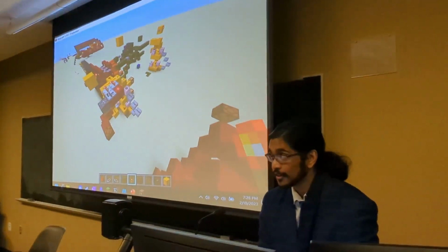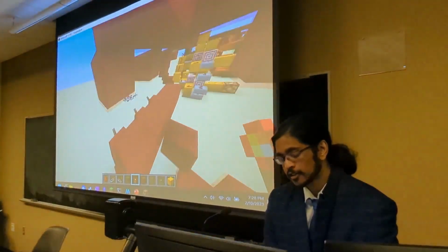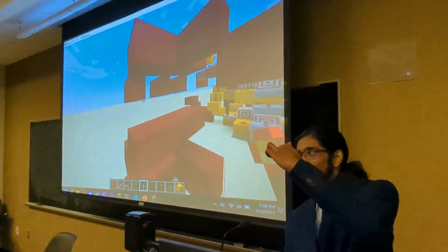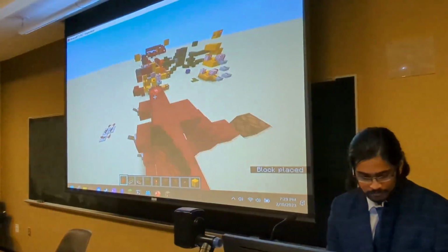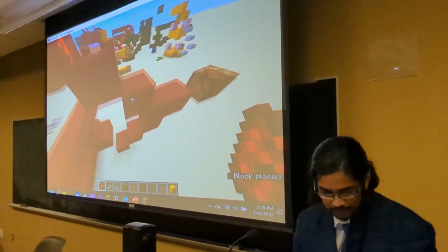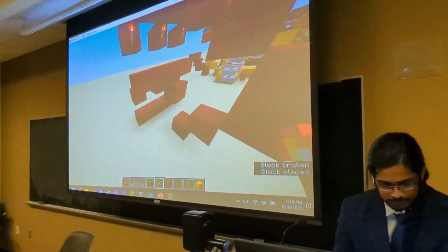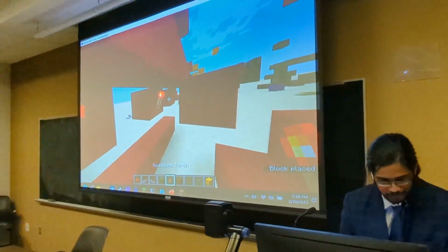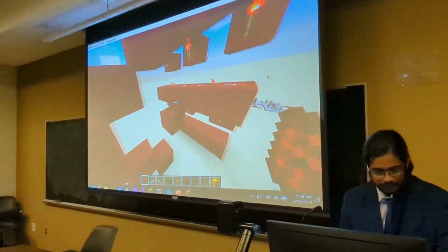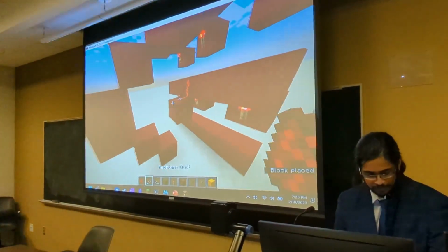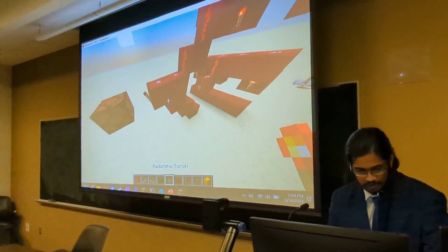Okay, so now we got the memory cell done. Next part is win detection. So all we need, first of all, is to make sure all 3 of the occupied inputs are turned on. So we just create a 3-input AND gate like this. Like that. And then for this guy, we can create another 3-input AND gate like that. And then just take the inverse of that and give it to our friend here.